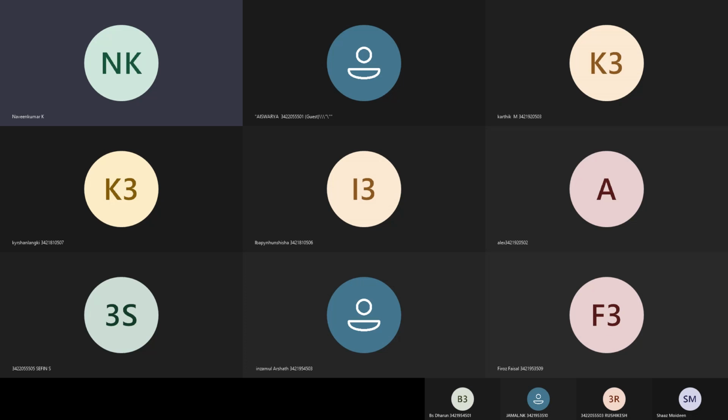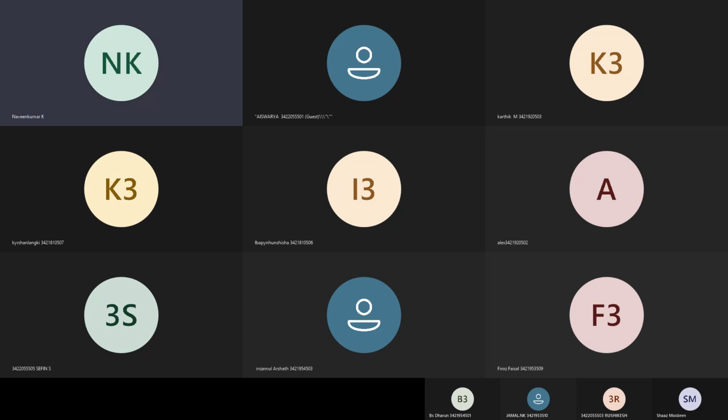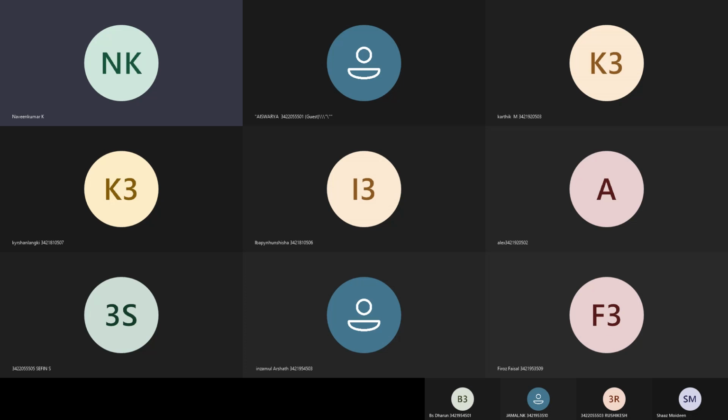In one direction, we got the structure laid out as 25 mm dia bars at 140 mm spacing. In the other direction, we are going to provide 12 mm dia bars at 125 mm spacing.